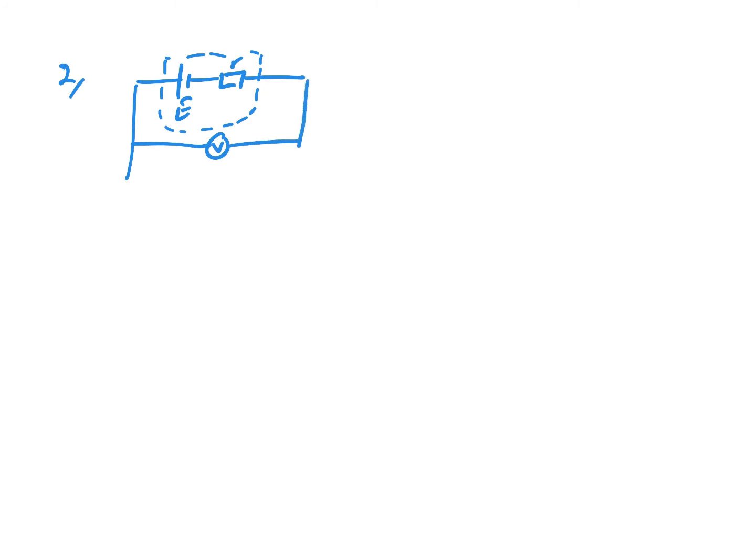There are actually 2 forms of that, but one's much more common than the other, so we're going to focus on that one here. And basically you would set up a circuit then with your realistic cell. You would have a voltmeter across the terminals. Incidentally, it doesn't matter whether you put the voltmeter across the battery or across the resistance in the circuit, because there's only one component here. But then you would normally make your capital R a variable resistor, and lastly you'd have an ammeter in the circuit as well.